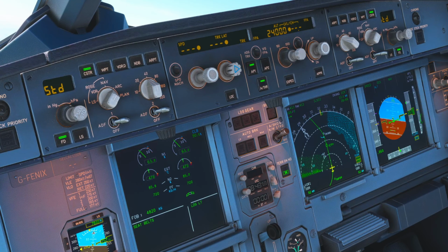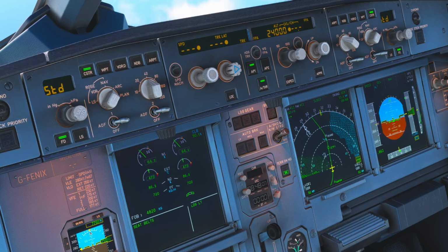On the final approach, the pilot compensates for the wind effect. Rotate the altitude knob to set a target altitude. Pull the vertical speed knob to engage the selected mode. Push the HDG TRK FPA pushbutton. This engages the FPA mode. Rotate the vertical speed knob to adjust the target angle relative to the ground.